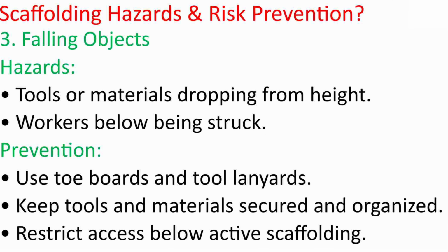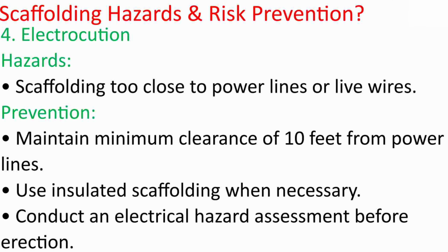3. Falling objects. Hazards: tools or materials dropping from height. Workers below being struck. Prevention: use toe boards and tool lanyards. Keep tools and materials secured and organized. Restrict access below active scaffolding.